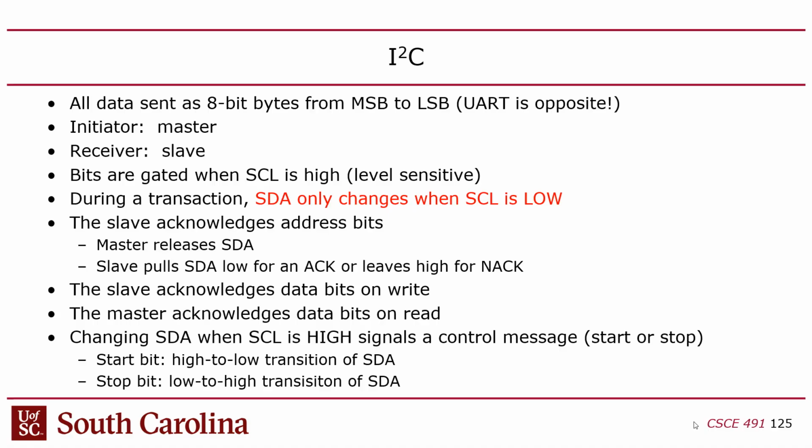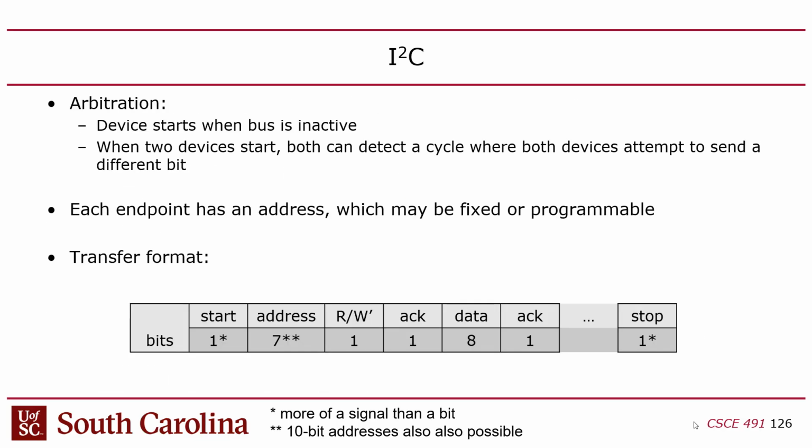Okay, so the idea is that I2C is 8-bit, like SPI. The master is whoever is initiating a transaction, and then the slave is the targeted peripheral or I/O device. Now, of course, those roles can change because it's multi-master, multi-slave. So let me actually skip forward here. So the way it works is that when the bus is idle, because it's open drain, the logic level on both the clock and the data are 1 when it's idle.